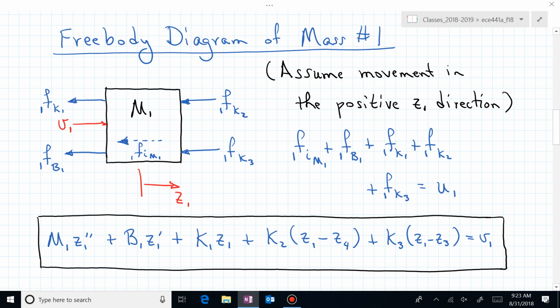And the dash pots are consistent with the springs. It's just that they produce a damping force that's proportional to the velocity of our masses. So if you could imagine maybe a shaft rotating in some heavy viscous fluid, the higher that velocity or rotation of that shaft, the more frictional force it's experiencing.